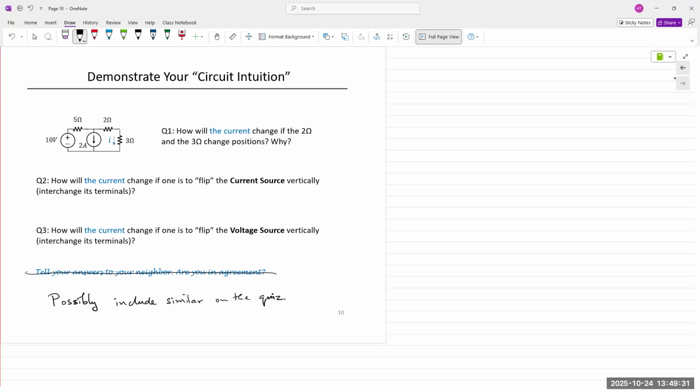One way to think about this is, let's look at the voltage source, right? Is the current flowing up or is it going down? It's going up, absolutely. So if you flip the direction of the current source, it's now pointing up. So if both currents are coming up and they're meeting at the node, how do you think it affects the other current that's leaving the node? It'll increase. Because instead of being in opposition, it's now summing up.